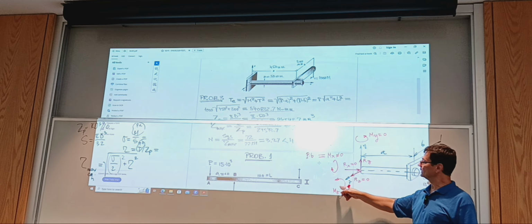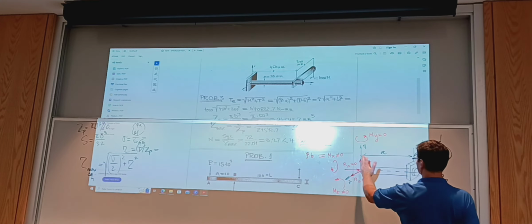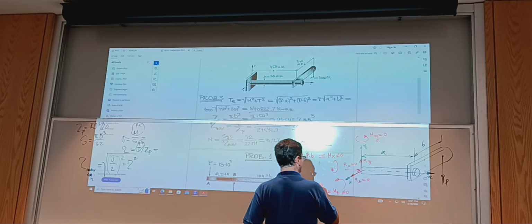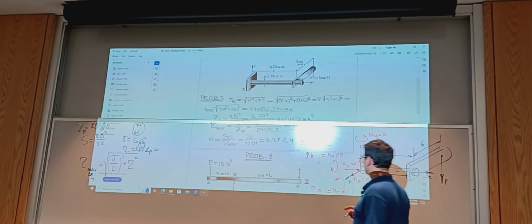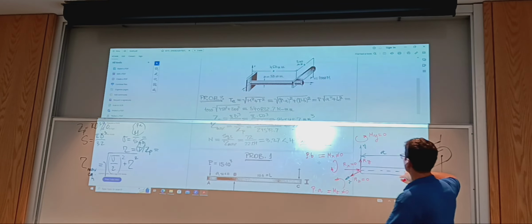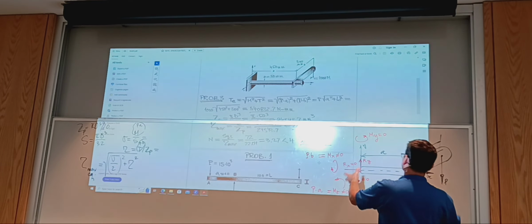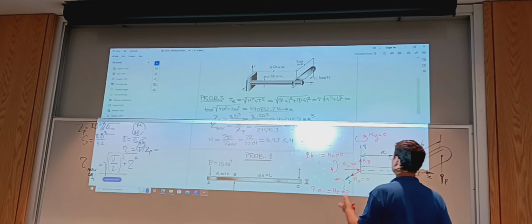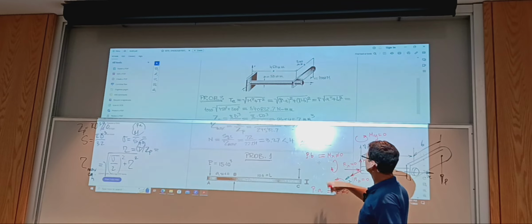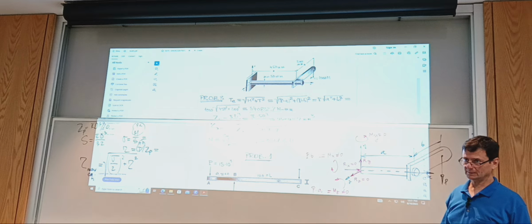This is the bending moment at the encastration, and its magnitude is going to be P times A. As for its orientation, the force wants to rotate the unit in the direction that is negative of Z, but I have this moment oriented as positive of Z. As for the earlier one, MX, I got it right from the beginning.